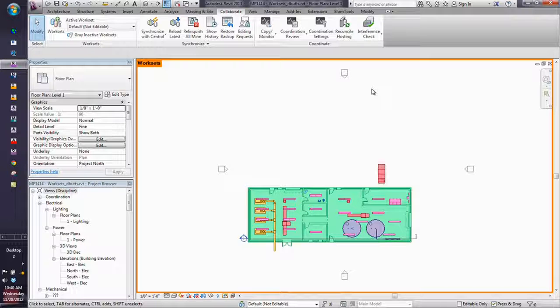And I did that in a couple of my water treatment plants. I had all the chemical systems in a work set. I had all the processed water in a work set. And then I had all the secondary systems, the ancillary systems, and the building supply systems in other work sets. So we just did a little color code like this and had them set up, and we also used color fills to make them print out in color. So it's a real quick way to actually see where everything's connected together. You ever work in a project where you got a lot of stuff and everything gets really jumbled? This is just a great way to take a look at those displays in here.